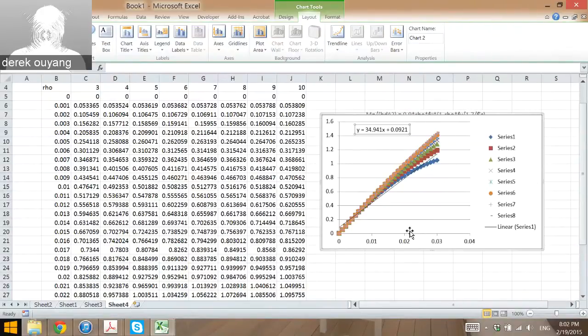And when you're talking about structural behavior of concrete, f'c is one of the least important things compared to your depth or your b, your width, right? Those kinds of things. So hopefully that's just something that becomes obvious when you use big data. And what that really means is that whether it's a linear trend line of just 3 KSI or for all points, this is now your design equation, right? Not for the real thing, but for that first feasibility check.